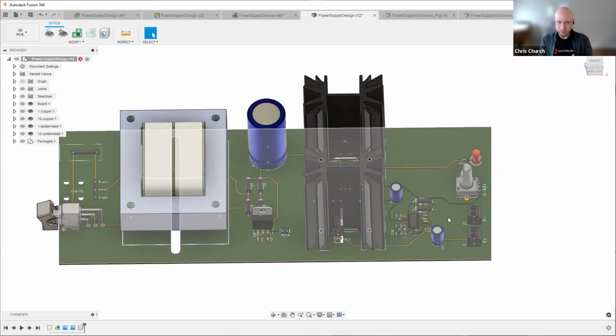And with the in-circuit test, it's a little less flexible than flying probe because what we would use is a fixture that's kind of set in one design, but that's in line in the SMT process. So we want to make that as easy and as cost effective as possible. So if we had a lot of SMT here, we'd put all our test points on one side preferably. It makes it real easy. We only have to develop one fixture. It's very cost effective. Likewise with flying probe, we can use the actual pins on components like these guys here, but it's often unreliable. So we're still going to want to add some test points for those devices.